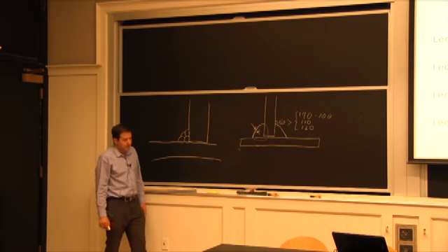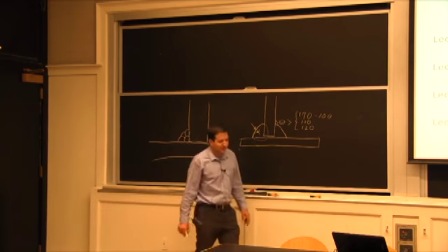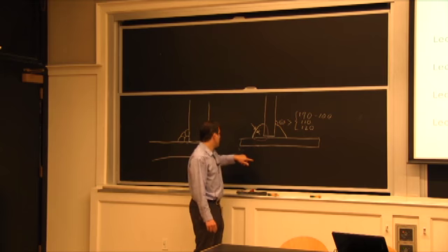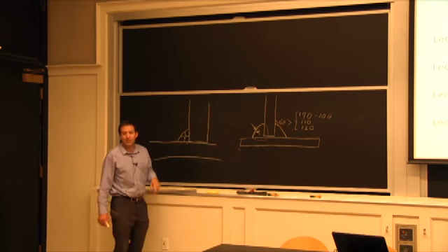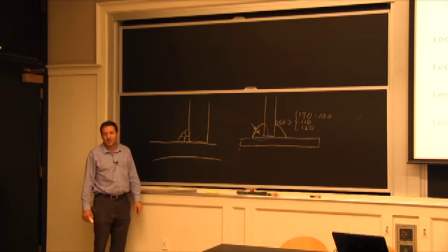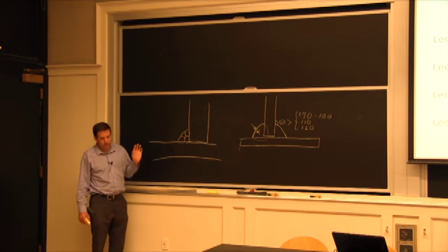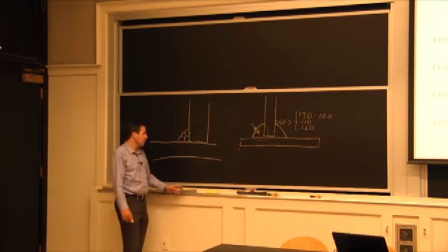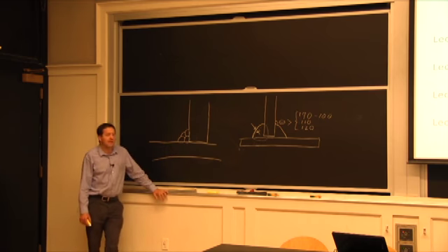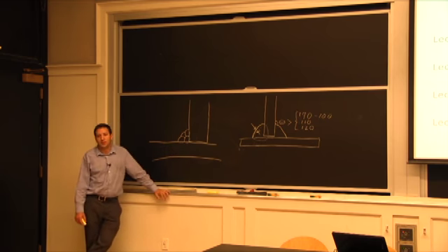When we talked about this, if you just ask for a weld, you get a weld. Sometimes people will say, well, I want a half-inch weld. Well, this is a half-inch weld. This is also a half-inch weld. Maybe this is a 1-inch weld. Is it okay also to have a 1-inch weld, but that's not fused? So this is where it comes in to say, well, you got to do it by ISO. You got to do it by AWS. The Joist Institute also has some welding requirements. ASME has welding requirements, and they're all different.